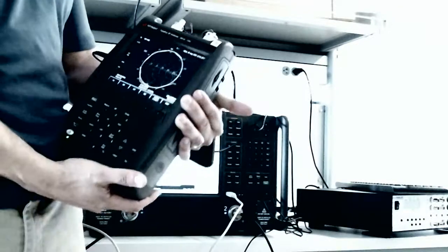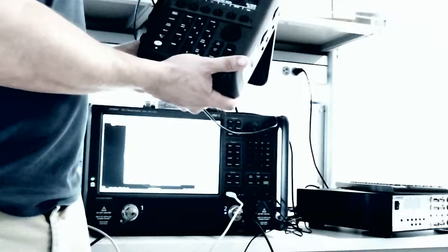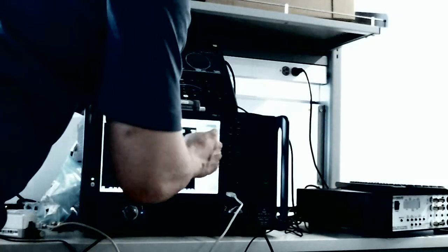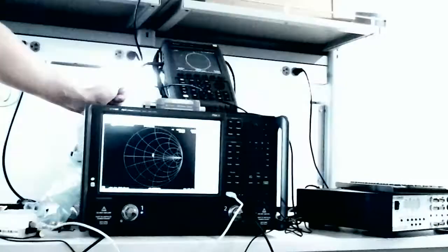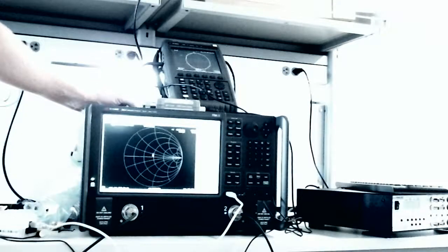Can the VNA give us the reflection coefficients? Yeah, absolutely. That's what S11 is, right? That's what you were measuring here. You were doing it versus power as a power sweep. But if I went to frequency, every time I change it, I have to do a count, because here I did it for 3 points, but what I was showing before was a sweep versus frequency.